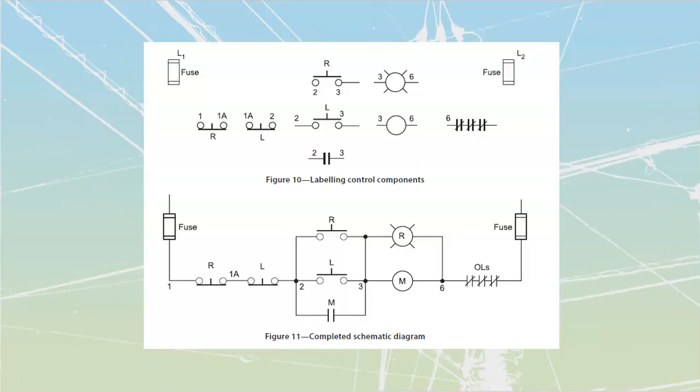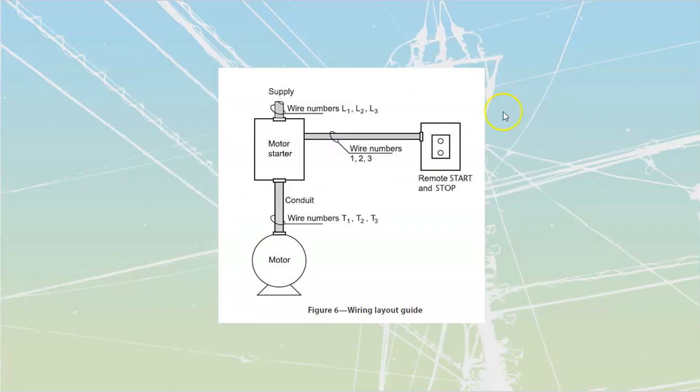Last thing that I want to look at on this one, by the way, is the way that my components are inside of here. You remember this thing where you have to figure out the number of wires to pull? The stop-start station that we're going to have for this one is going to look a little bit different. There's going to be a second conduit onto it, and a second starter box. It's going to have 2 push buttons, and it's going to have a light off of it.